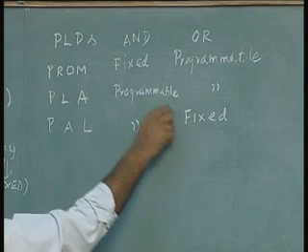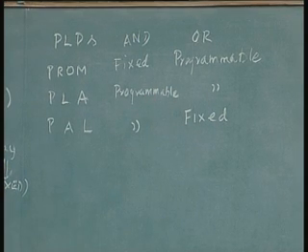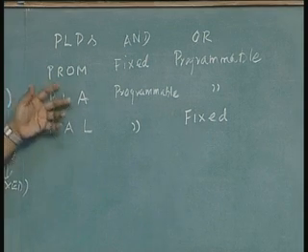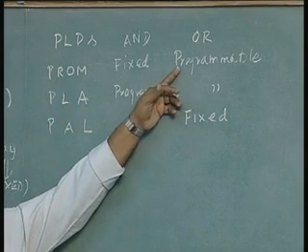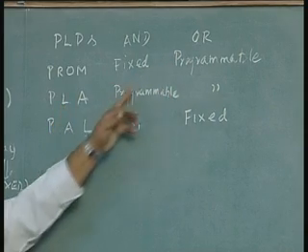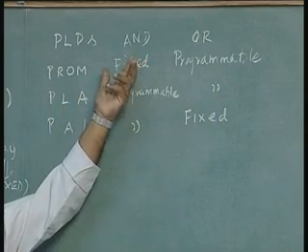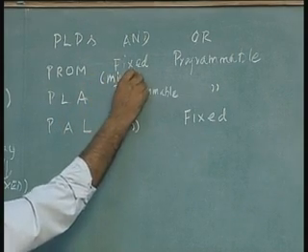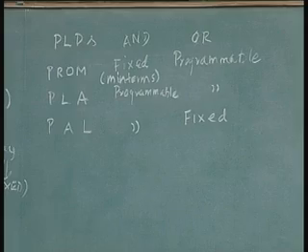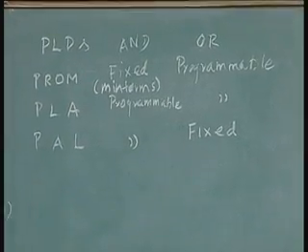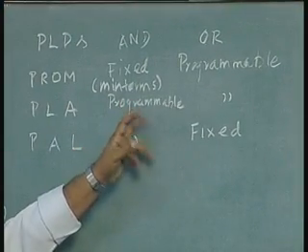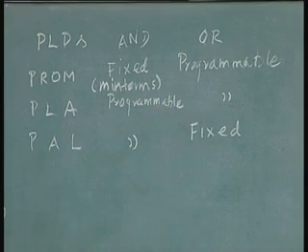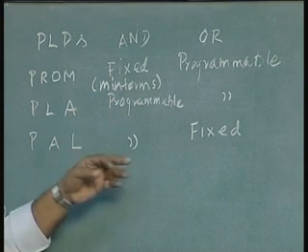But why do we go for this from here to here? That means we are going one step backwards. This is the historic evolution. PROM was first done and then the PLA. The reason for going for PLA was that the fixed AND gates generating all the min terms was an inefficient way of using the product terms as well as consuming a lot of silicon. So, they thought of programming this so that we will have programmable options. So, this becomes more efficient implementation wise.